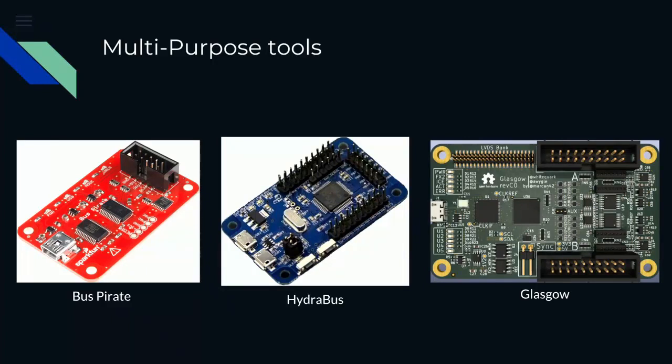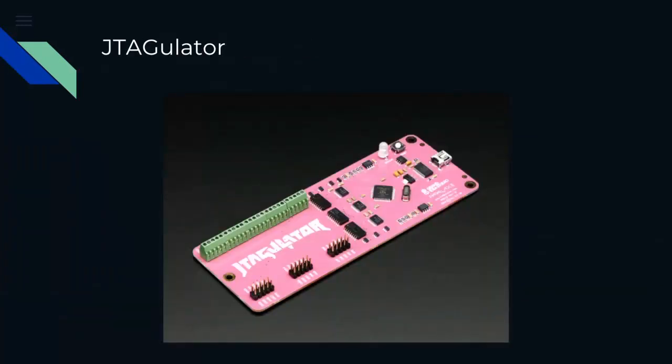And the other one, GreatFET, is a tool that is going to have an FPGA and a microcontroller itself, with some voltage protections and configurable volts. So I don't have one of these, but I think this is going to be a very cool one. Another tool we do have, JTAGulator. Basically, when you have identified some pins on the board and you want to identify which ones are JTAG, use this tool. It performs a brute force attack on the pins and tries to identify which ones are the JTAG pins.